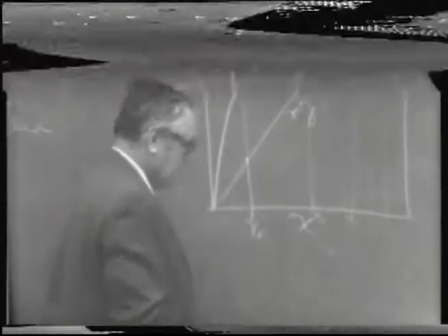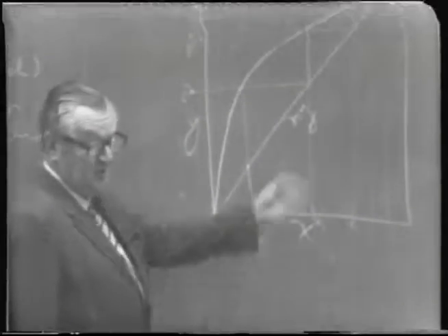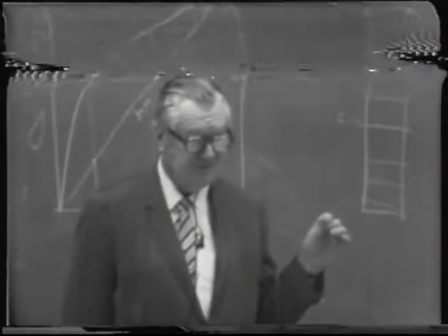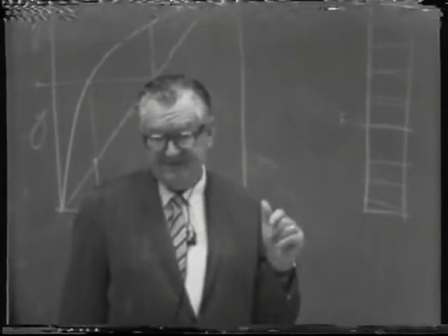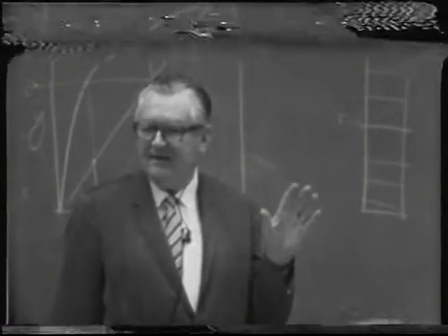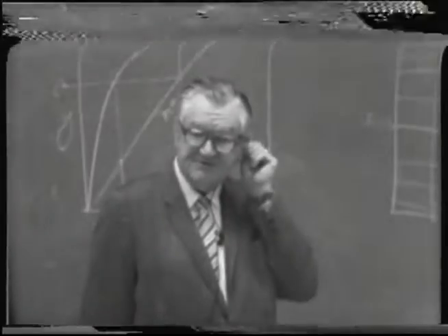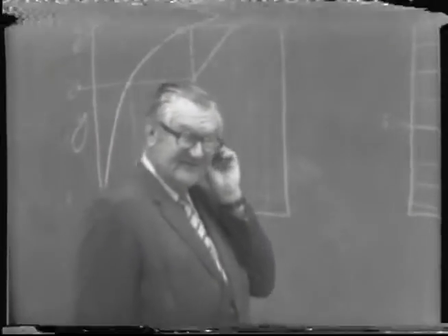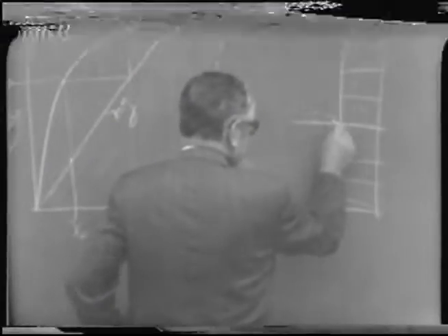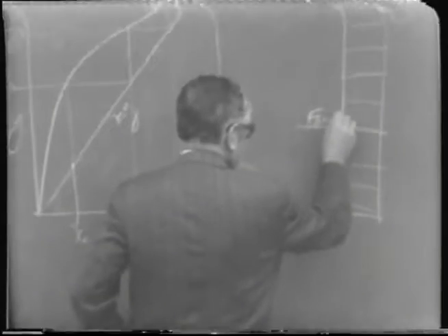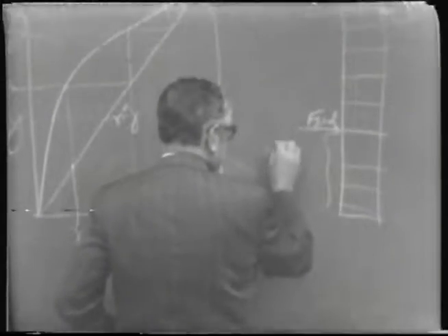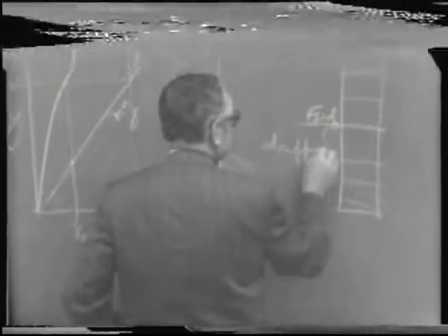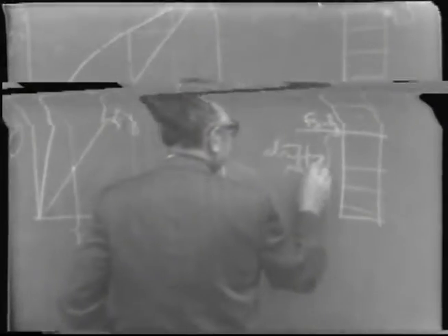we have what we call operating lines again, comparable to the term I used here applied to flash distillation. We will be able to develop a system whereby we have an operating line which represents the process conditions, and then we'll have an operating line for the stripping section of a column. If this is the feed, we call this a stripping section, as you recall.